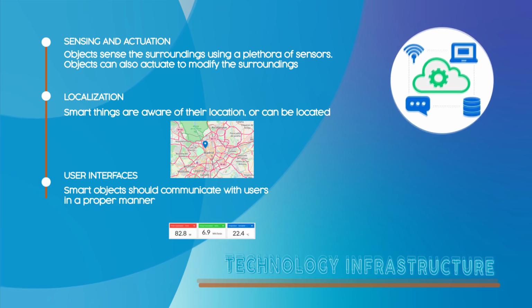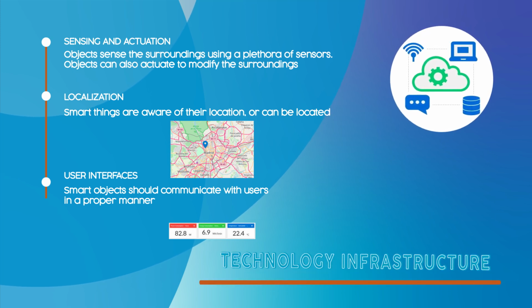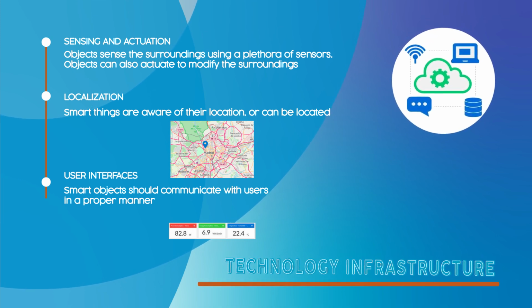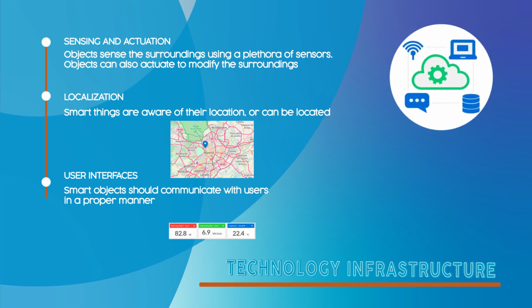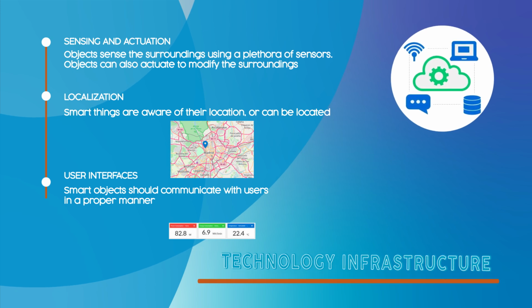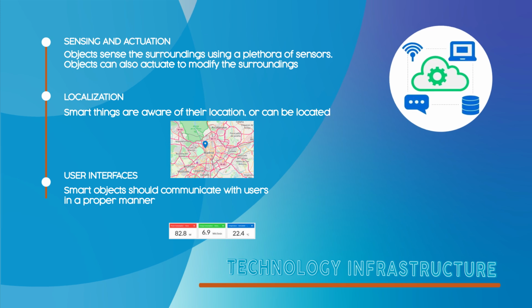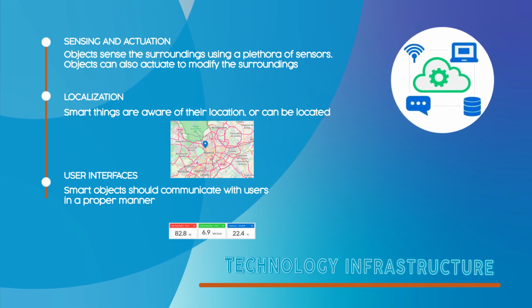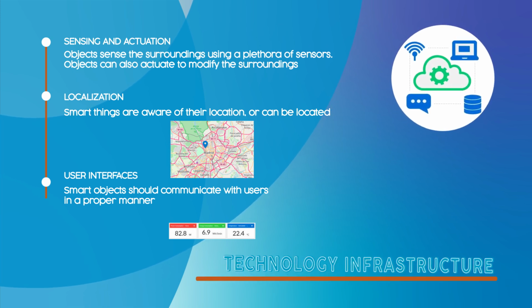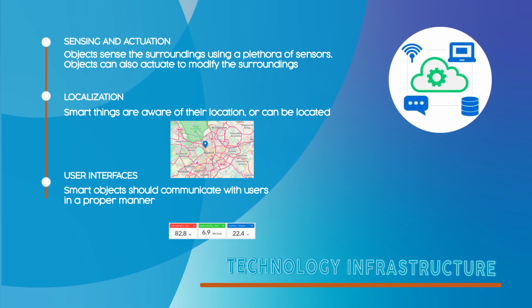The identification of the smart objects must be performed physically by the DevEUI, provided by the manufacturer. During the registering process, the DevEUI is associated with the ID that identifies the smart object in the net, and the AppEUI, or ID of the application server, which is the destination of the messages sent by the nodes.